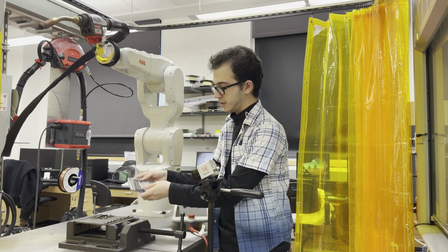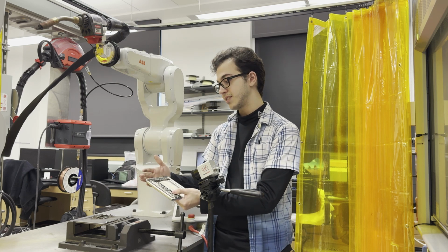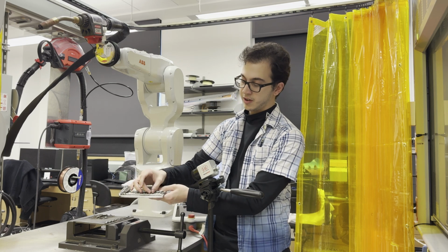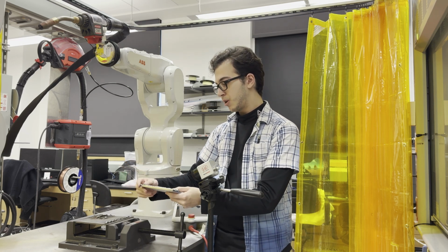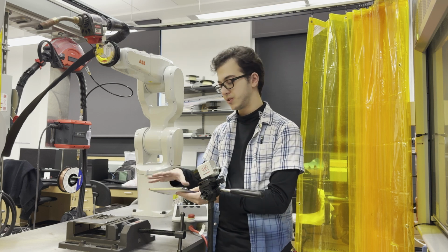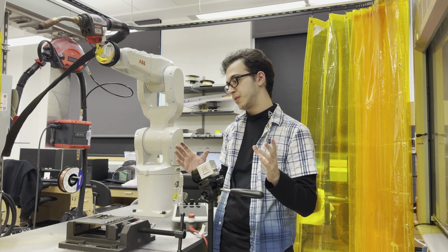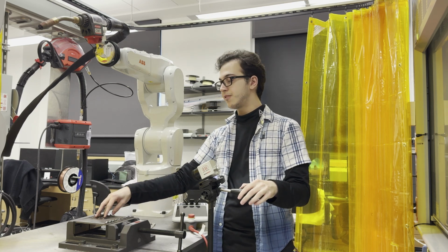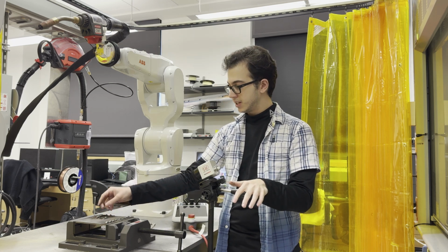Another issue is I have another plate right here. This is actually aluminum. When we originally started, we were testing with aluminum, and you can see we had some rough welds at the start, very bubbly, but also some very smooth welds with multiple layers. But what we ended up finding was that the emissivity of the weld itself was too high. So this camera in particular was not able to capture a clear image of the melt pool, as opposed to carbon steel, where it was able to effectively capture the melt pool itself and be able to see.